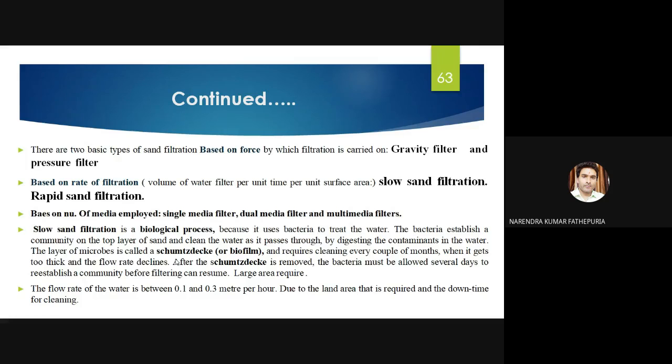It's a Dutch name, how you will pronounce. So it's a biofilm which will be on top of the layer on the sand, because sand will be having a smaller particle than gravel. So the first layer will be working as a biofilm. It will capture all the microbial bacteria in their pores, and it will help to remove these bacteria. So it helps in biological treatment